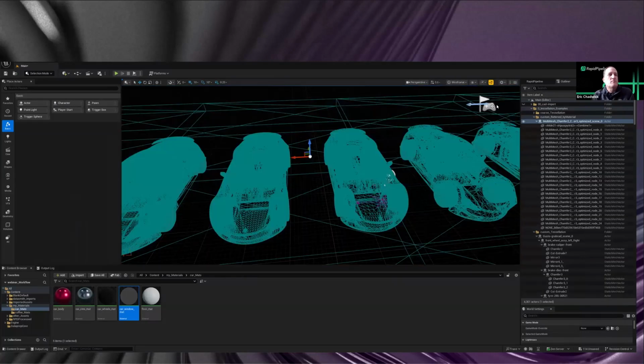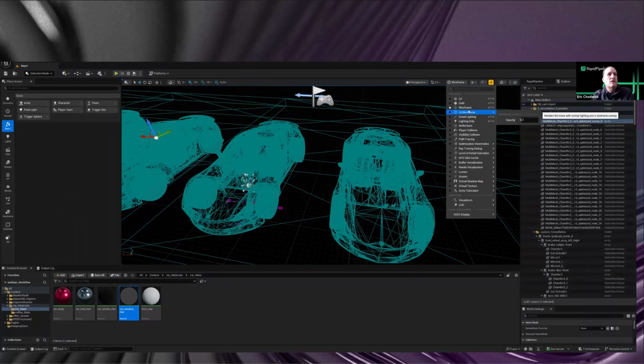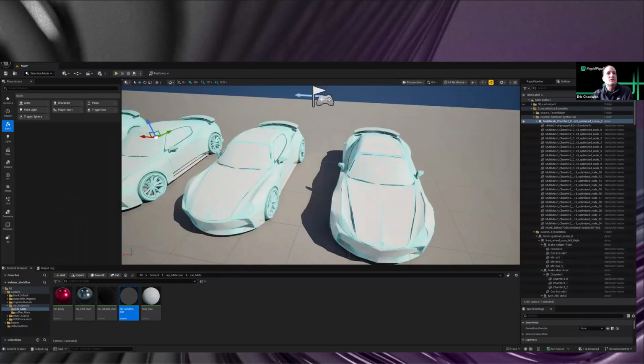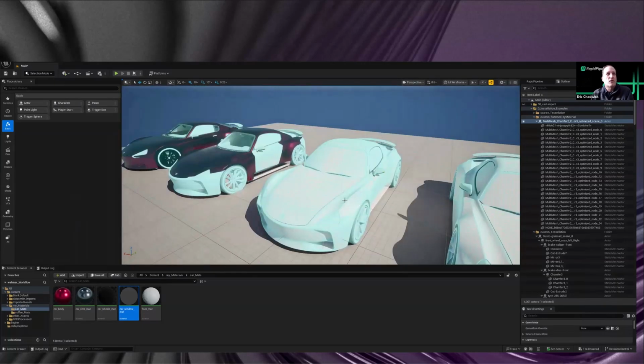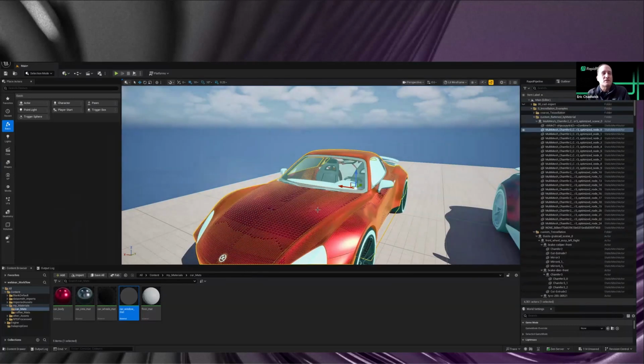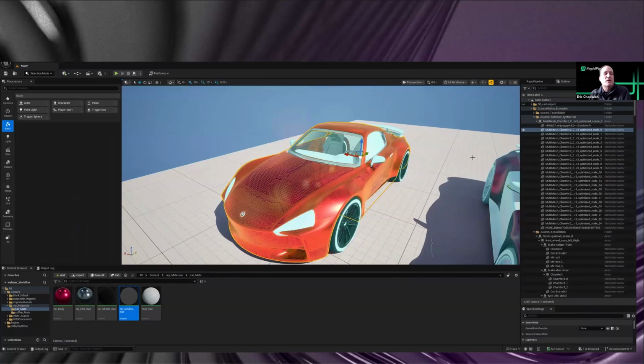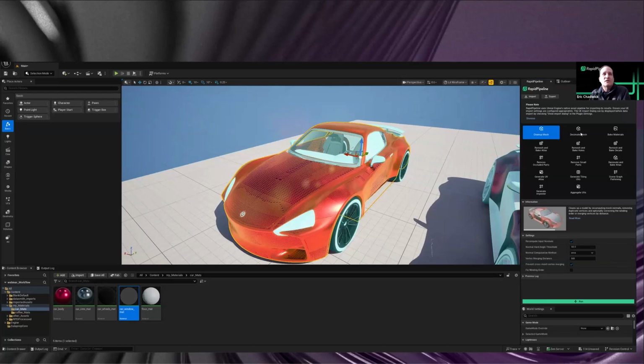But if you import at the highest resolution and then tell RapidPipeline to do the decimation, you get a really nice result. You don't get all that blockiness because it's aware of curvature and it's adjusting the model based on deviation from the high-res source. Whereas when you're just bringing it in at the lowest tessellation, the algorithm is not aware of that. It's taking each patch and trying to figure out how to tessellate that alone. Anyway, sorry to interrupt.